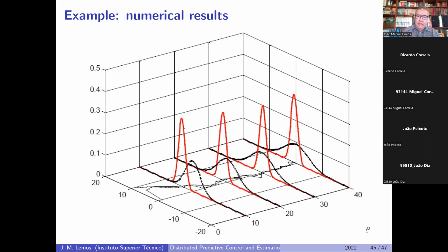When I consider the linear case, if I start with an initial error that is Gaussian, everything stays Gaussian. So I can just propagate the mean and the covariance. And if I do the algebra to find this mean and covariance, I get the equations of the Kalman filter. So one possibility of looking at the Kalman filter is the first one that we considered before, the unbiased least variance estimator, and I get some expressions.